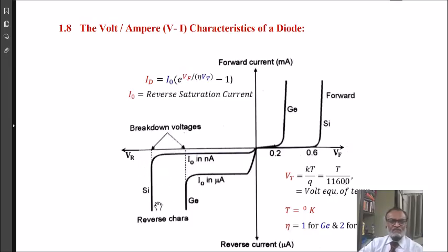And we observe that in the breakdown region, the voltage across such avalanche or Zener diodes is mostly constant, right? Current is increasing or decreasing, but the voltage remains fairly constant. And this happens after the breakdown voltage called VBR, or reverse breakdown voltage, also called the peak inverse voltage for the PN junction.